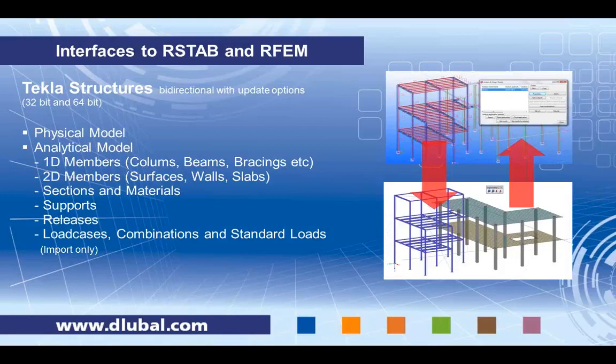In addition to solving the transition from the physical to the analytical model, we can also handle or include support and release information inside the Tekla model, and load cases or load combinations, as well as standard loads inside Tekla. Those are the most important objects that Dlubal software can retrieve from Tekla models.